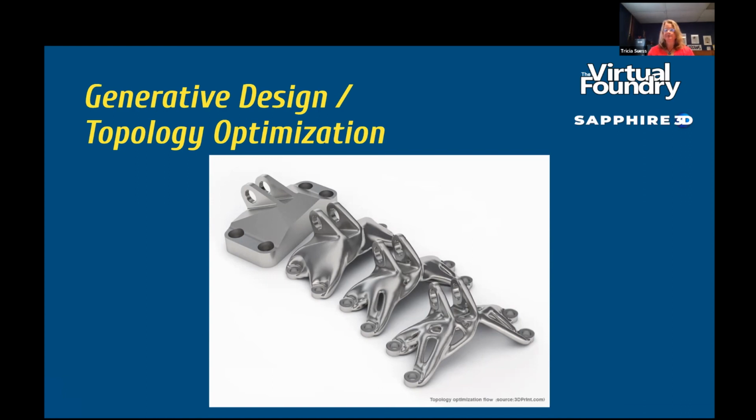Right, and the material savings is a crucial point because you're using so little material that you can use some things that are more expensive. You wouldn't think of machining a titanium part like this, but designed for this process, you're using 1/10 of the amount of material. So where previously titanium may have been prohibitively expensive and not made sense, it might make perfect sense from this perspective.